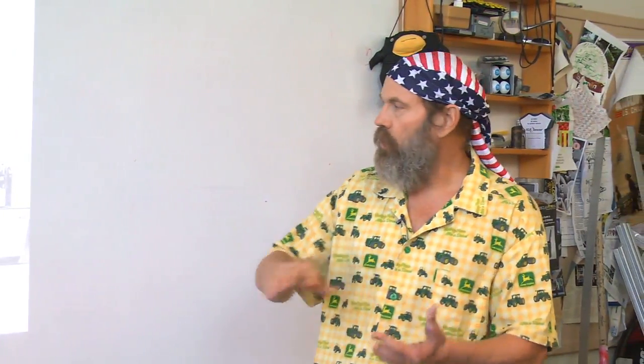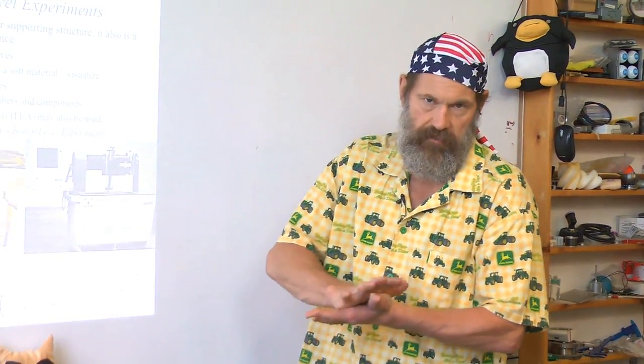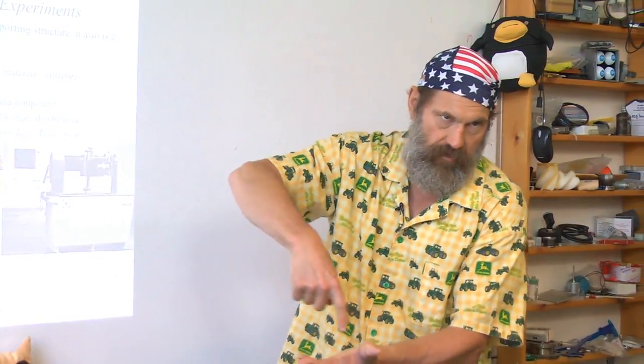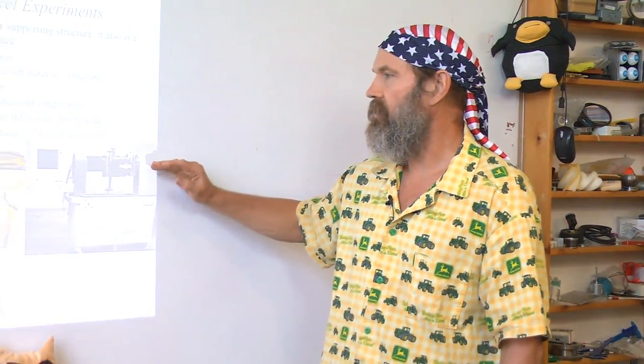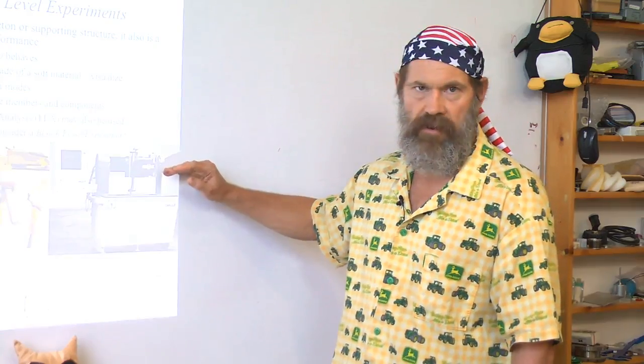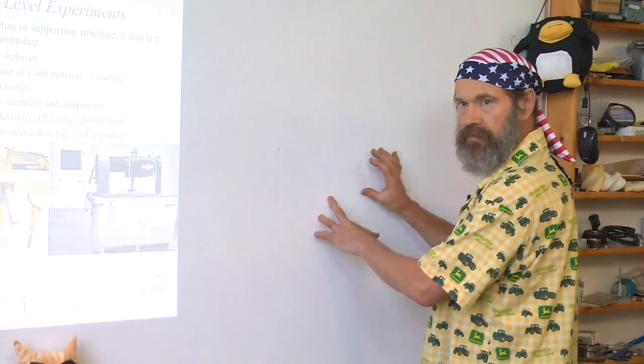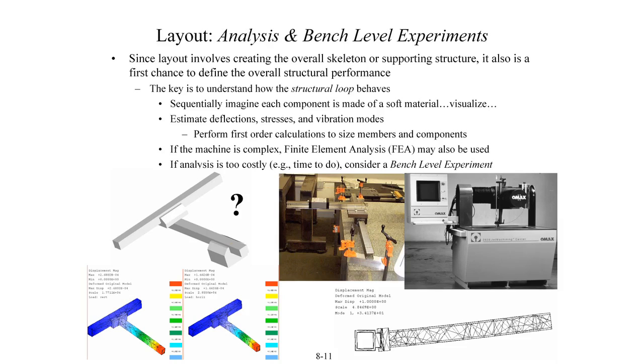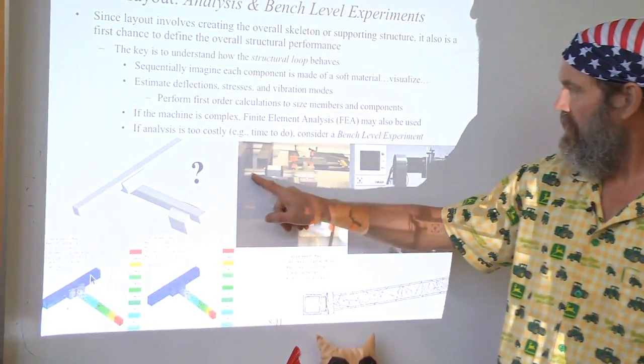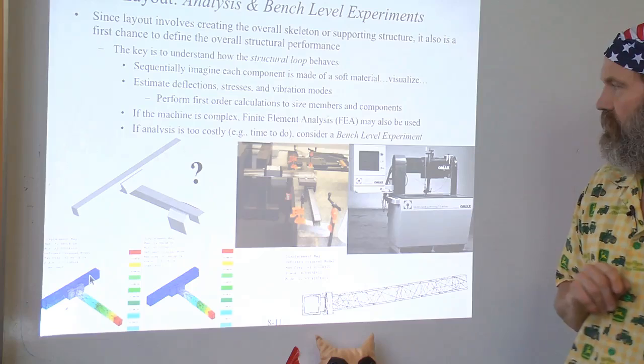And there's no real load capacity on this machine because the abrasive water jet cutting process doesn't put a load on the part like a milling cutter. But under its own weight as it moves, it can't be deforming so much to cause unacceptable errors. A key thing is it's got to be low cost. So one of the topics we looked at was, how can we integrate the function of the bearing in the structure? And it went from some first order sketches, just like we did here, to some solid models and finite element analysis to look and see, could we use the bearing rail itself as the structure?